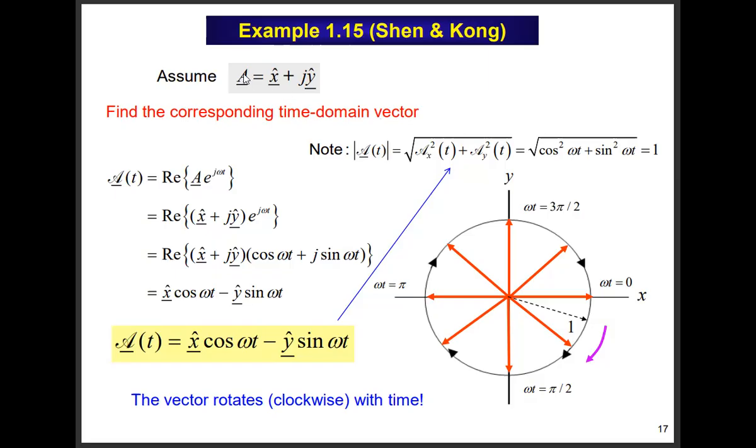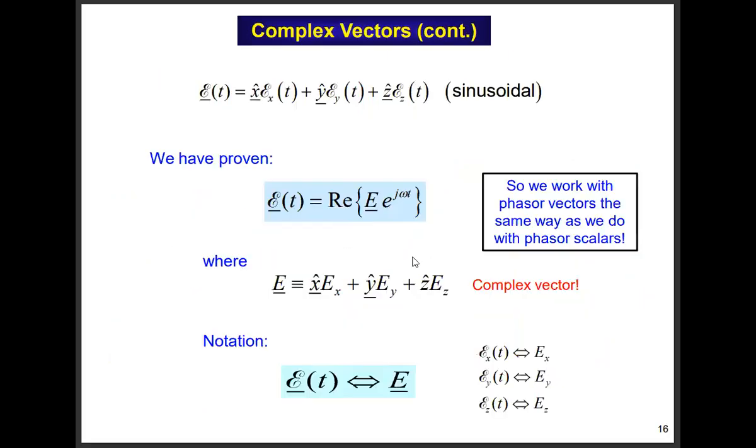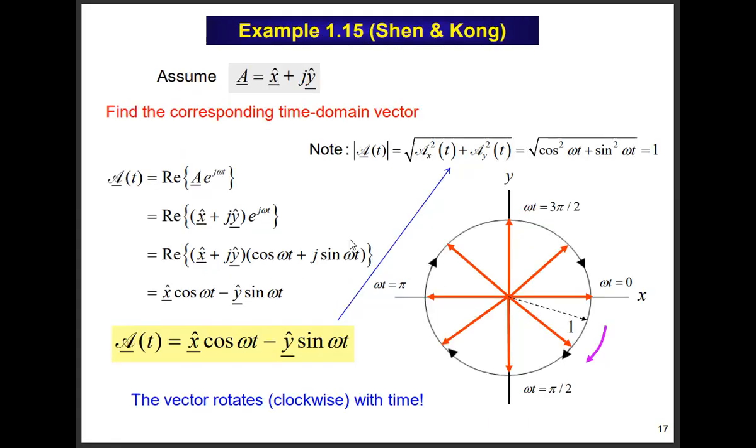Okay, so notice the notation: the regular Times Roman math notation in the phasor domain, and what I call the hand script SF font in the time domain. Hopefully you downloaded those fonts, by the way. Okay, anyway. So time domain A is the real part of phasor or complex A, e to the j omega t, right? Just like I reviewed over here, right? Okay. All right, so just plug in. There's the A. Of course, the A itself is a complex vector, but not a function of time, of course, right? But the time comes in when you say real part of that times e to the j omega t.